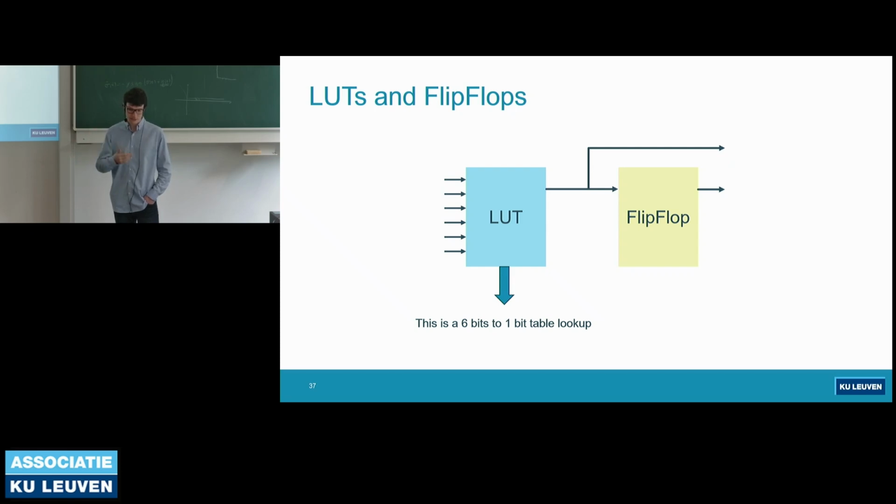Because in software, you're stuck with the instructions that you have. And so you get a multiplication often in about the same amount of cycles as an addition. Not on all architectures. It's going to depend on, like, do you do this for ARM? Do you do this for MIPS? Do you do this for RISC-V? Your mileage may vary.